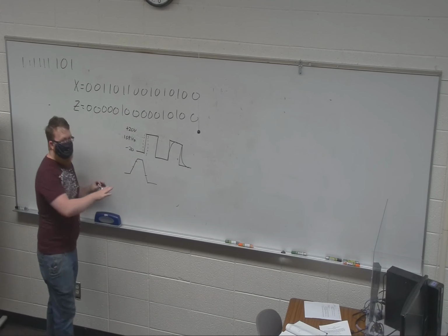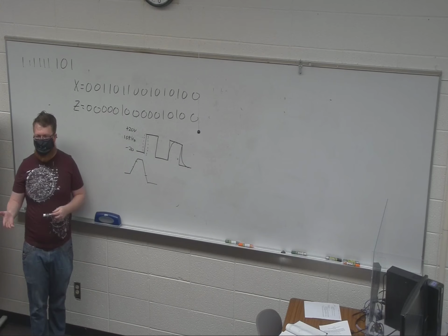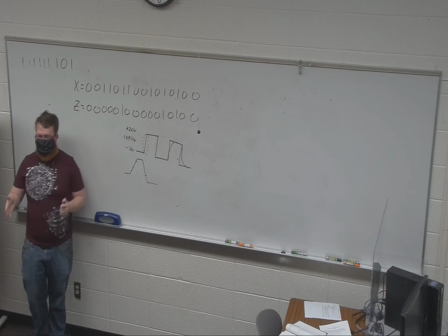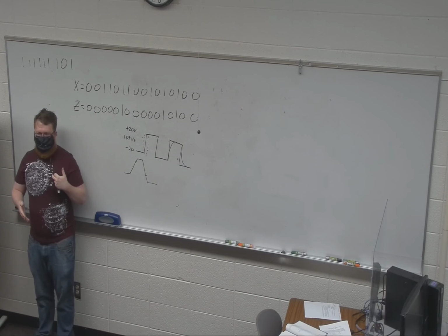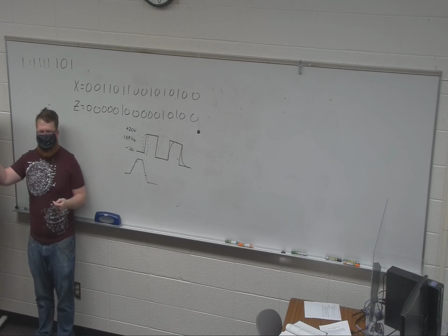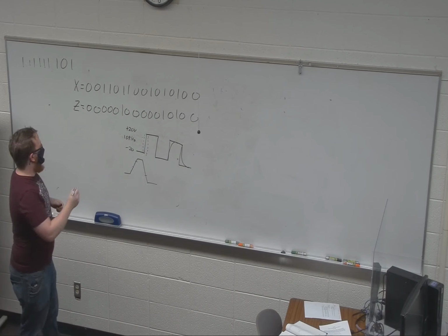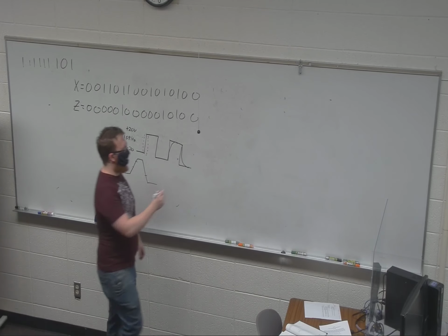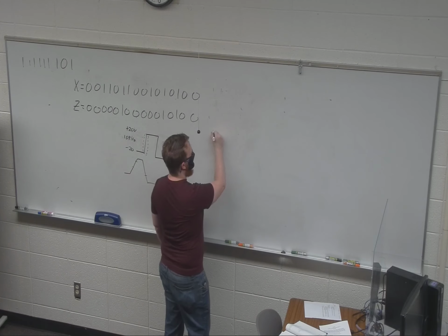So when we have that and we start thinking about clock timings, on a flip-flop specifically, you're trying to read in new data, right? So the D flip-flop has new data coming in and it wants to output it at the Q on the next clock. So if I have the clock, I'm going to draw a new one.